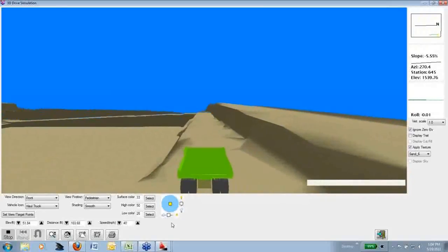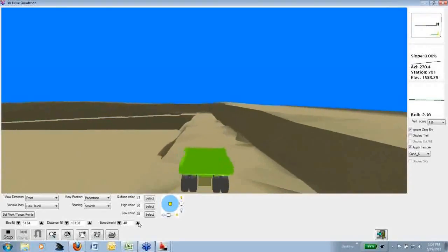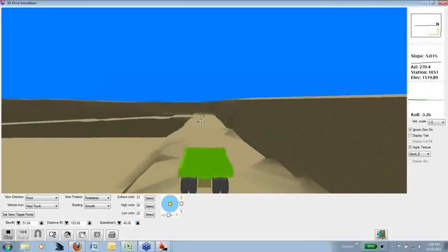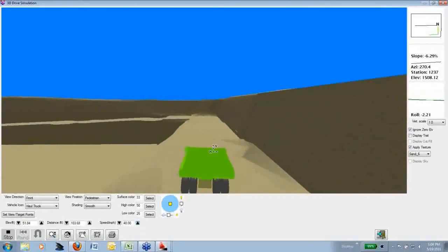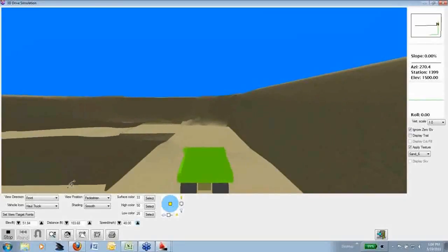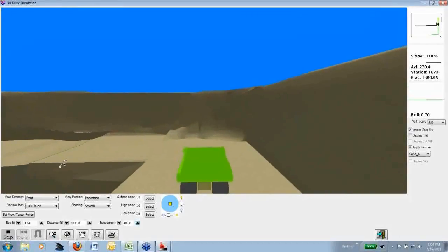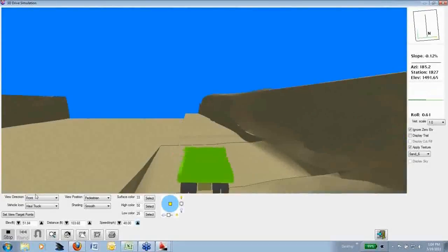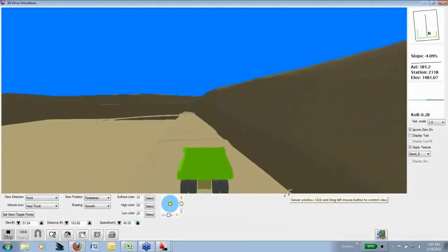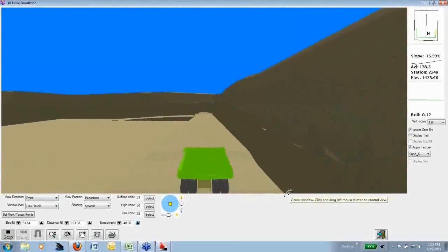And the original pit floor was right here, so we extended the ramp and went down to elevation 1400 down here. Looks like there'll be a little bit of a drop off here, but after that it should be a constant 5% ramp going down. And that's about it. That finishes the quarry design I had planned for today's webinar.